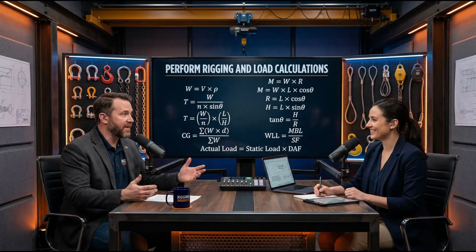Let's actually walk through this specific case study provided in the Bechtel sources. Imagine a rigging crew preparing to lift a massive 50-ton industrial module using 4 slings. Okay, 50 tons. A rigger throws a tape measure on one of the slings and finds it is 29.7 feet long. Then they measure the straight vertical distance from the crane hook down to the lifting lug on the module, which comes out to 25 feet.